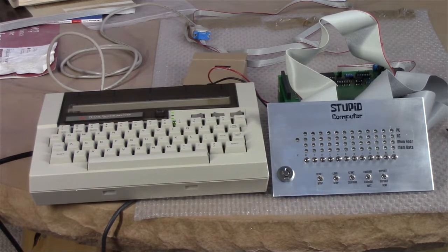What I did is in the debounce circuitry, I gave the stop switch a longer time constant so that when you power on, the reset will come off of the reset condition before the stop switch comes off of the reset condition. So it tests at the very beginning of the microcode whether the stop switch appears to be pressed. And if so, it says, oh, this must be a power on reset. I can run the power on self-test. Otherwise, it doesn't. So let's run our first test.